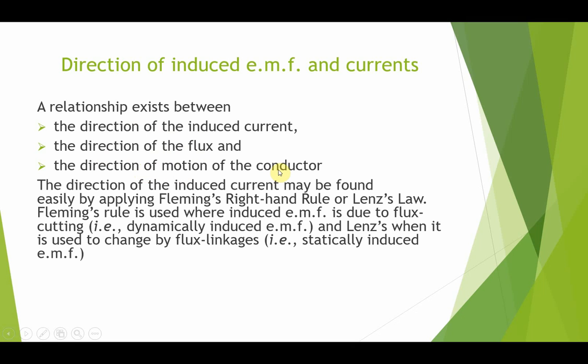The direction of the induced current may be found easily by applying Fleming's right-hand rule or Lenz's law. Fleming's rule is used where induced EMF is due to flux cutting, that is, dynamically induced EMF, and Lenz's law is used when the change is by flux linkages, that is, statically induced EMF.